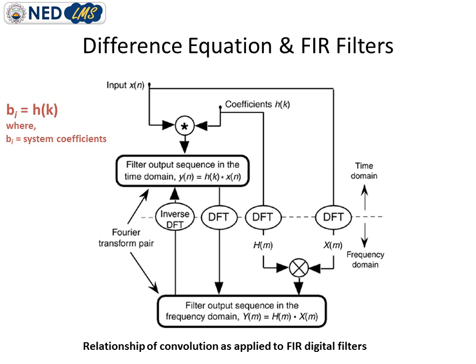It is very interesting to note that the vice versa of this operation is also true, which means if we multiply two signals in time domain, then convolution occurs in frequency domain. So these two are a transform pair, convolution and multiplication. If we are multiplying two signals in time domain, then their spectrums get convolved in frequency domain.